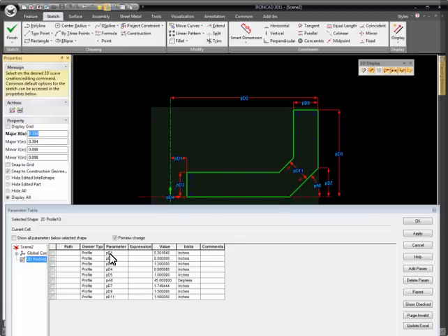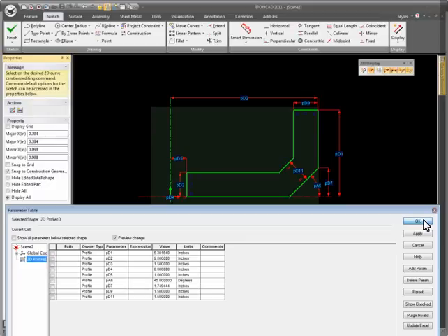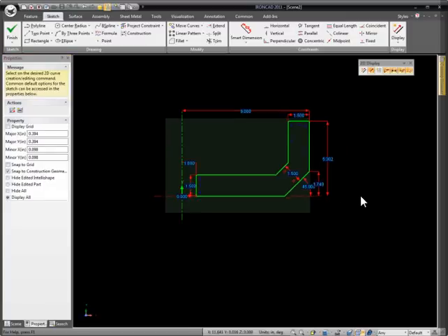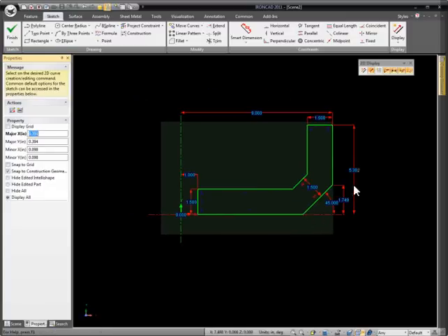You can rename these parameters, tie expressions between those. For example, maybe you want the height and the length to be an equation between each other. You can actually put expressions in here, say PD2 is PD1 divided by 2, half the distance or something like that. Those are very usable expressions to help define or control your geometry for whatever particular use the user is trying to drive. In our case, we don't need to do that, but if we do want to adjust some